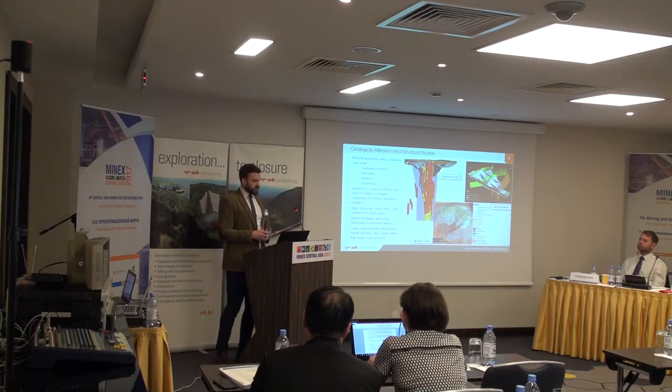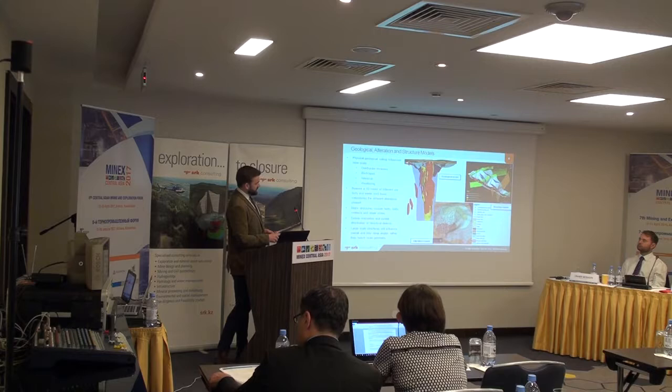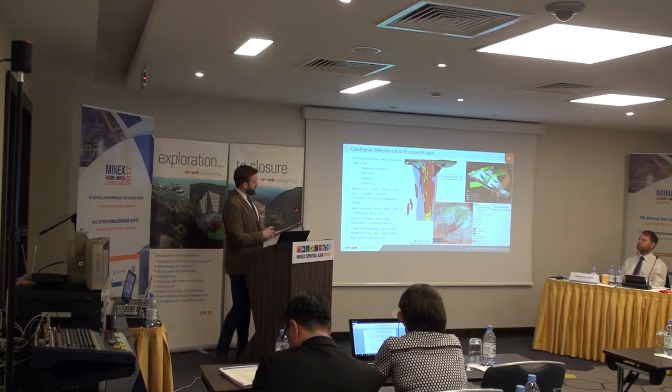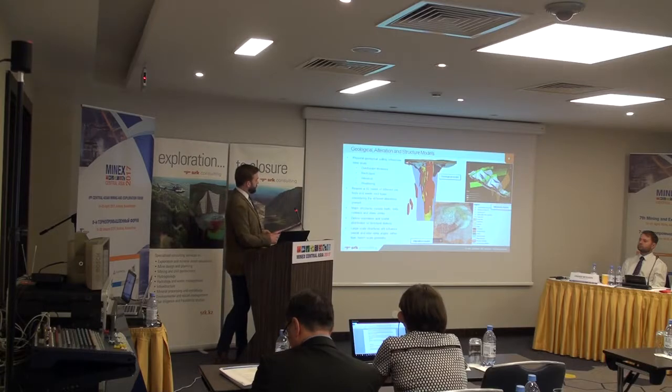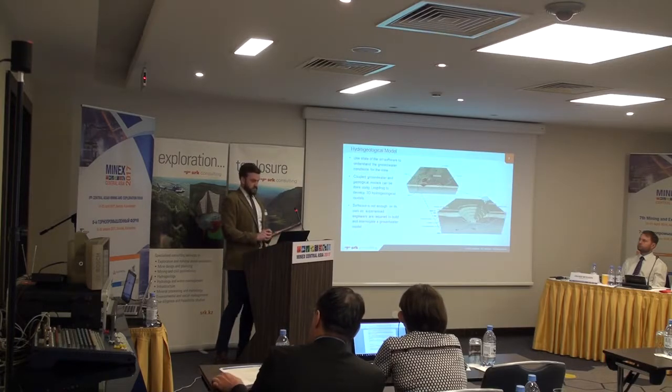And you require a 3D model for different ore body and waste rock types. And the major structure model is also something that's very critical to your geotechnical model, to understand where these large faults and structures may lie in a pit. And it's really these large-scale structures that will influence the overall and inter-ramp angles rather than your bench-scale geometry.